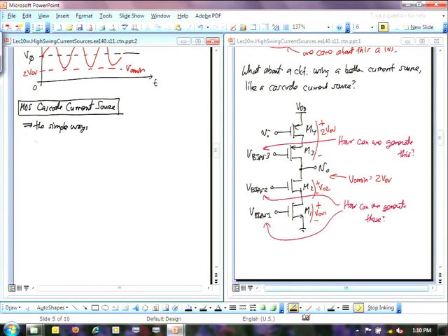Right? So I'll have a VDD here. I'll have some current source here, which, as you've seen before, you can generate by just putting a voltage across a resistor. But I won't draw that just yet. But then once I generate this current here and I want to repeat that into this circuit on the right, one thing that I can do is just stack some transistors and do a replica type biasing like we've done in the past.